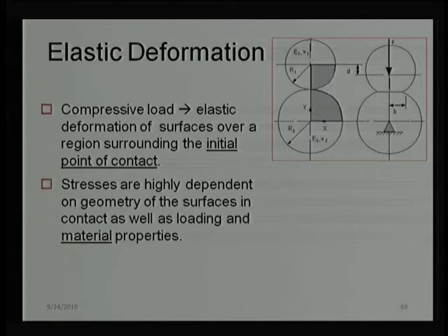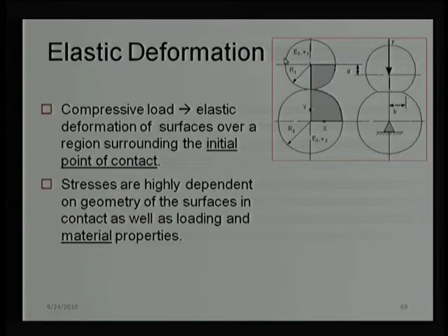To account for both cases, viscosity variation as well as deformation, we need to find out what the elastic deformation will be under different conditions. That is why this slide comes. We need to find out the elastic deformation of the surfaces. Initially, we are taking very simple geometries, say sphere on a sphere, cylinder on cylinder, which are convex geometries. After deriving the equation, we can extend this to concave or flat geometries also.